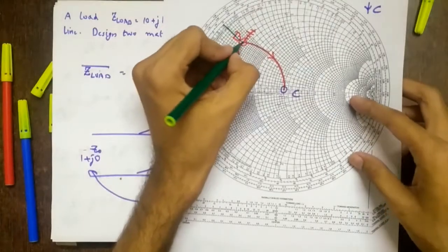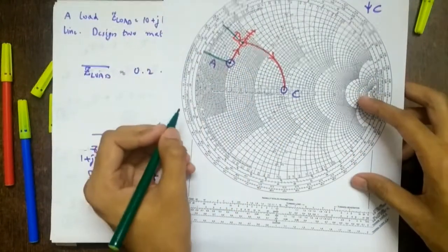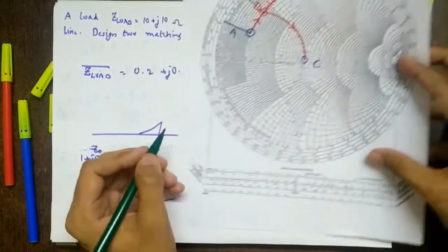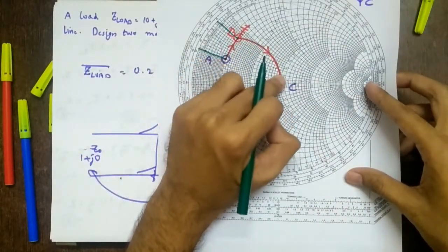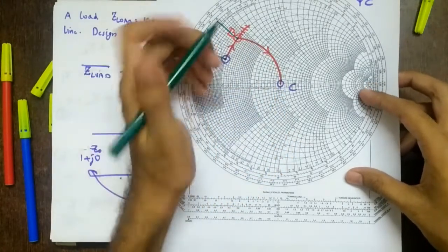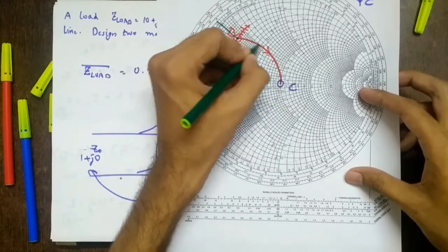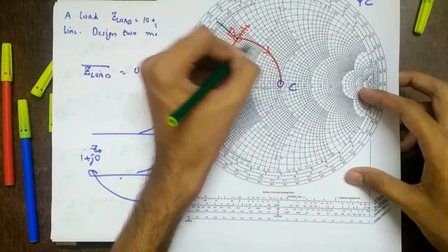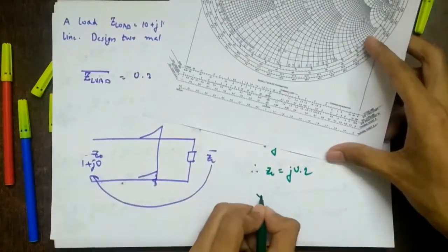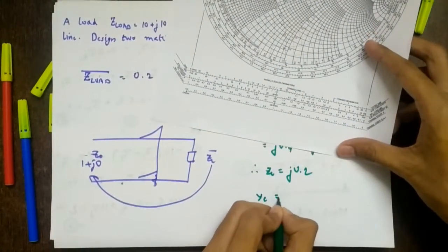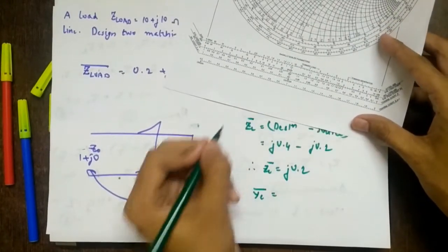Right? Next, we have moved from B to C. So destination minus source. And what is it? A capacitor. And we have moved along which line? Dotted line. So it is an admittance. This is very important. Again I am repeating, we have moved along a constant conductance circle, right? Because it represents a dotted line, so admittance mixture. So it will give us what? Admittance. And it is what? Admittance of capacitor. So YC, small yc, equal to, it is in normalized form. If you want, you can give bars.